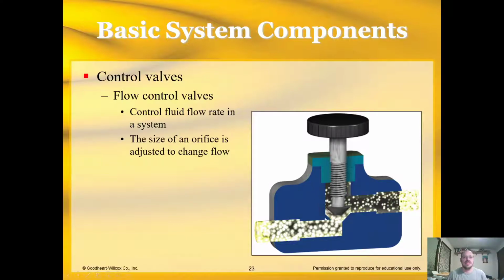And that's typically done with one of these called a needle valve. You can kind of see the way they try to show it with molecules, I guess. Water molecules flowing in, or hydraulic molecules, oil molecules, getting kind of compressed here. So you're going to typically have a higher pressure. You usually get some pressure loss, energy loss, pressure drops without any work being done. But you're able to, again, restrict flow. My usual example is putting your thumb over the garden hose, right? So that's kind of your needle valve there.